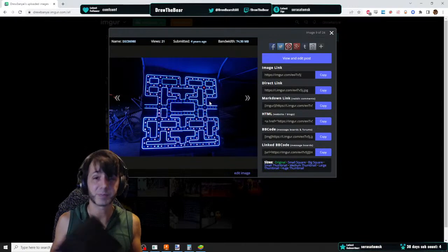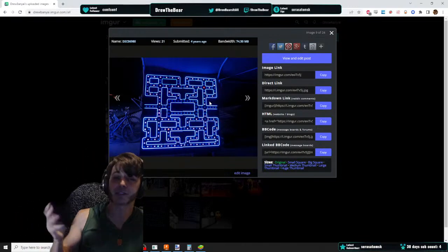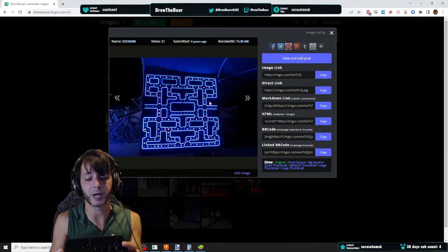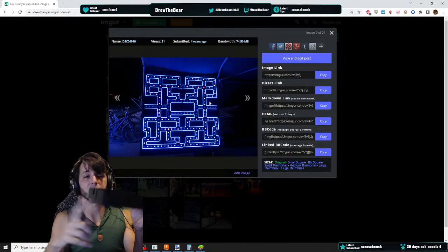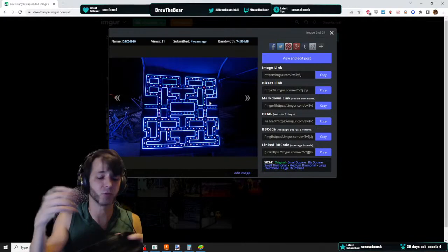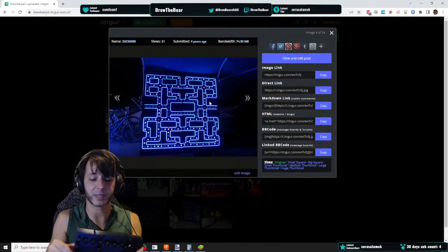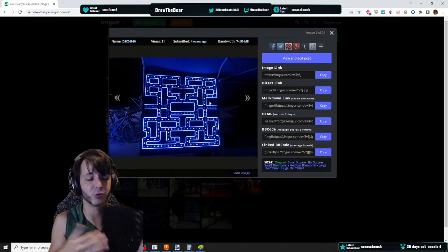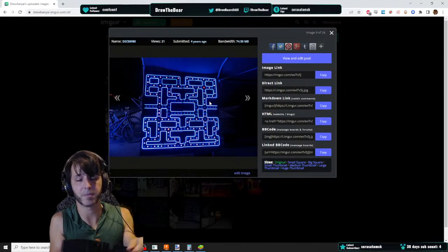which, this piece, let me just explain, does not look very complicated. I build it upside down, so I build it this side up, which means it doesn't need to fill in this area with support that I have to rip out. Basically, it also means that this side here is very nice and flat and smooth because it's on the bed, so it melts very nice.